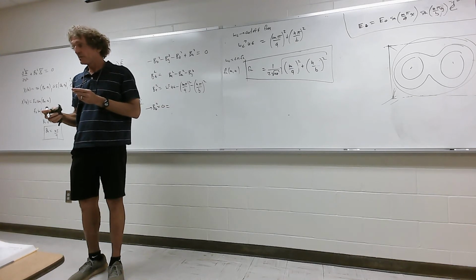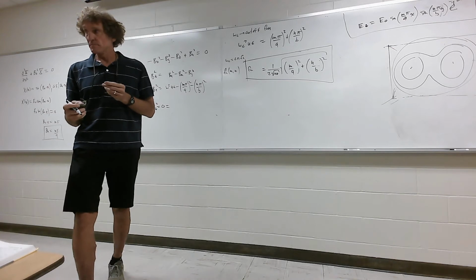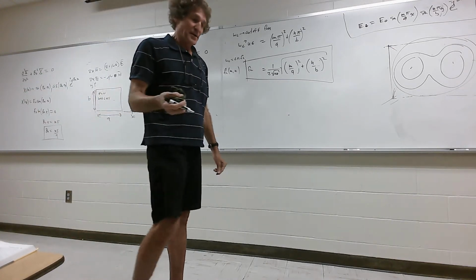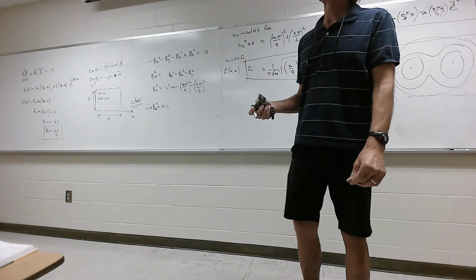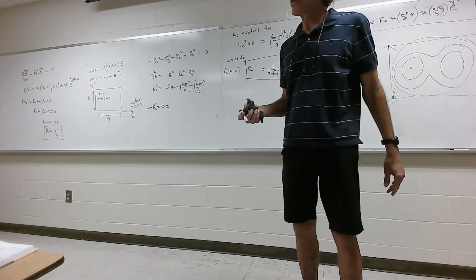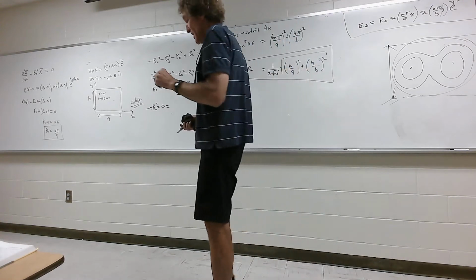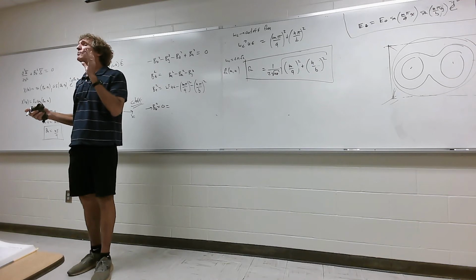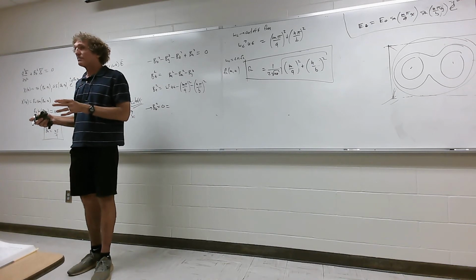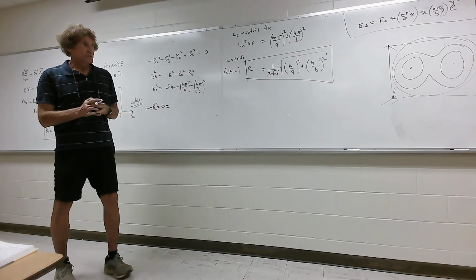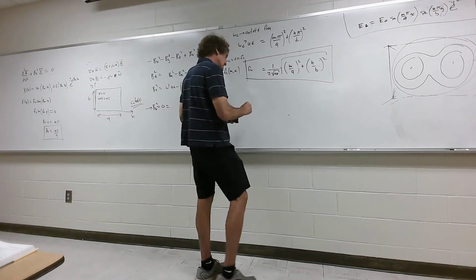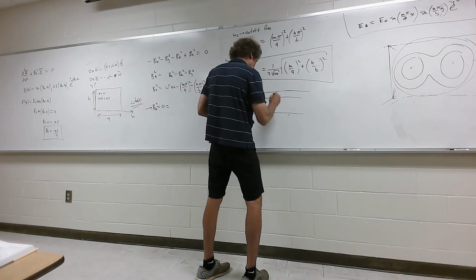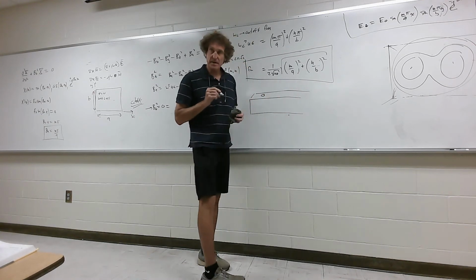So, in a waveguide, do we have any control over the mode, or do they all kind of propagate? Good question. Here's how you do it. I'm going to jump ahead. When we go through the TE mode, you're going to see that the lowest order mode that will propagate as a TE mode is the 1-0 mode. That is the lowest frequency that will propagate. Now, what they'll do when they're driving a guide, and I'm just trying to be as honest with you as I can without getting too deep into the theory, is cut a little hole in the guide.